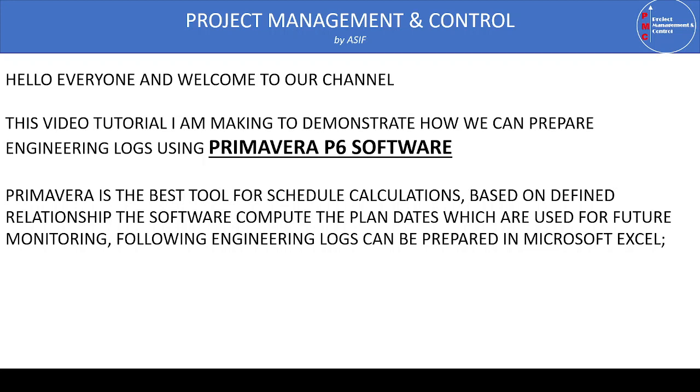Once we link our engineering activities with the construction activities, we can compute the early and late dates for engineering as well as for the construction activities. These planning dates are used for the future monitoring of the program, and in the same way we can use the engineering log dates for progress monitoring and update of the engineering activities.